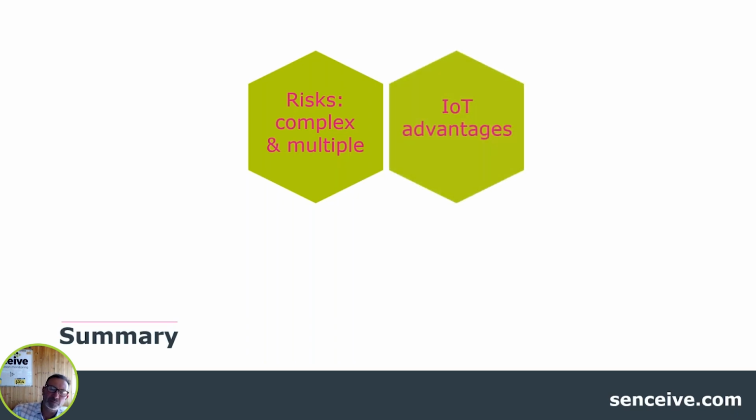I'd hope that we've demonstrated some of the advantages of IoT in terms of being small, easy, flexible, long life, low cost per year, flexible ability to take it down from one place to use it somewhere else, and the ability to provide high frequency sampling. For example, if you're looking at the stability of a retaining wall, where you can get data for sub-minute intervals.